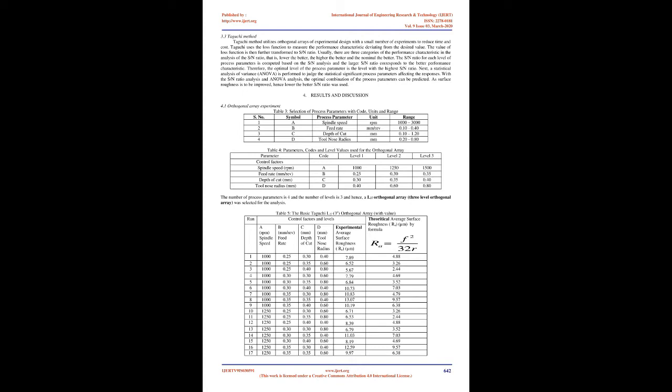Mkaladar et al. [2] applied Taguchi method to determine the optimum process parameters for turning of AISI 304 austenitic stainless steel on CNC lathe. It was concluded that machine surface roughness was affected mostly by cutting speed and material removal rate, MRR, was significantly affected by depth of cut.